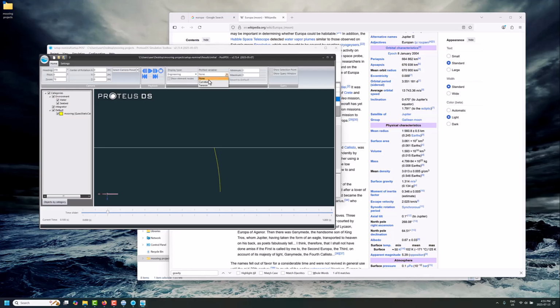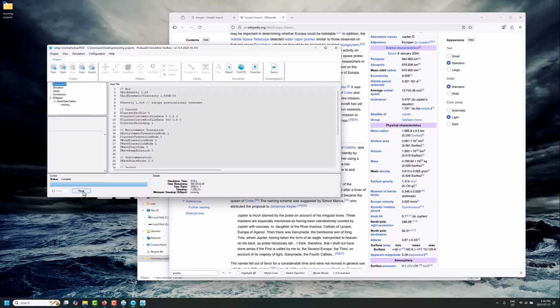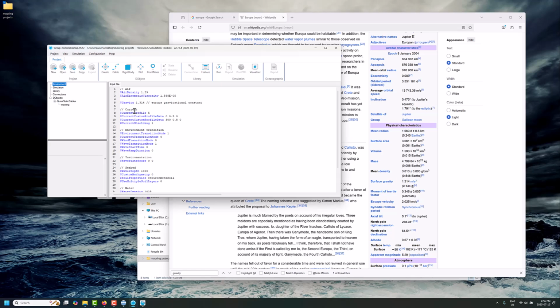So, of course, there's lots of details you can get into looking at all the numbers and more specifics. But really, what I wanted to highlight was the pitfall: be careful when you're looking at the parts library with wet weights that are determined in Earth's gravitational field. And then how you can go about setting the gravitational value. Again, this is a hidden property, so it doesn't show up by default, but you can just start typing and find it and then change the gravitational constant. Away you go.